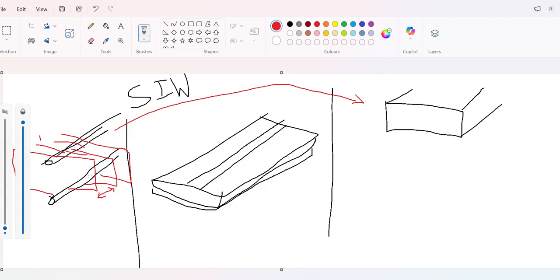Because of lambda by 4, this short circuit, due to quarter wave transformation at this point, can look like an open circuit, and your energy will fundamentally go through this line, and there will be a signal line and this return line. So this can be emulated in this structure also. The main signal current is going like this, and the current is coming back from this, and we have connected short-circuited extra lambda by 4 sections on both sides. Because of this, it gives you a lambda by 2 total dimension. This broad waveguide dimension becomes lambda by 2.